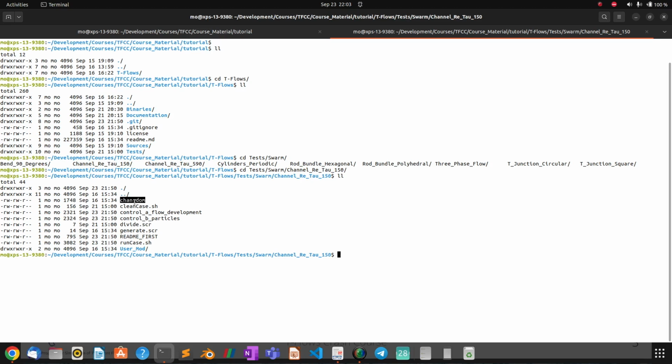And if you generate the mesh internally, then you need this .dom file, which refers to the domain, and the second file is the control file, which has all the input parameters. Just so you are not confused, we don't have two control files because we have two domains. We have two control files just for the sake of dividing the simulation into two phases.